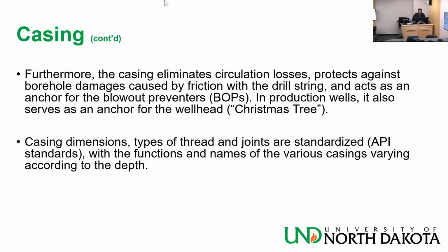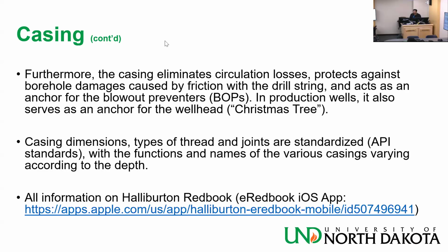Casing dimensions, types of thread, and joints are standardized, API standards, with the functions and names of the various casings varying according to depth. So Halliburton has this book, I have it downstairs, it's called the Red Book, which has all the standards, all the casings, what is the outer diameter, what is the inner diameter, what are the thread types, all the information that you need.